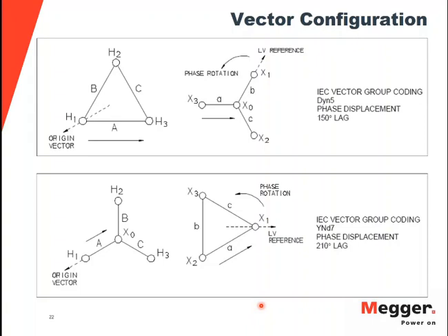So if you only do H1-H0, and there is a problem with the X1 connection coming to the center conductor and then to the top of the X1 bushing, you would miss out on that information. So it is very important that you cover not only the winding but also the bushing terminal, the connection from the winding to the center conductor. You have to take care of those things as well. So my recommendation would be to perform both H1-H0 as well as H1-X1.